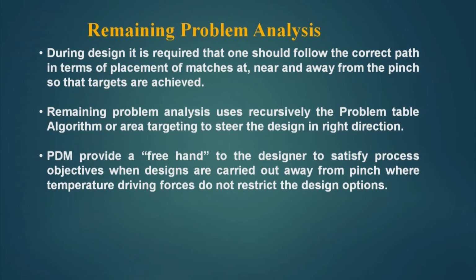PDM provides a free hand to the designer to satisfy process objectives when designs are carried out away from the pinch, where temperature driving forces do not restrict the design options. We have already told you that the PDM rules are to be strictly followed for pinch exchangers, and if you do not follow them, it will violate the delta T minimum criteria.